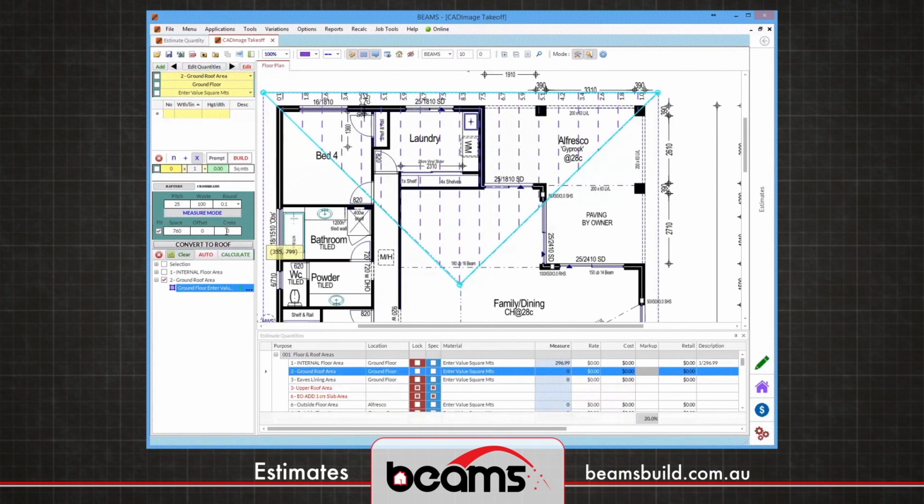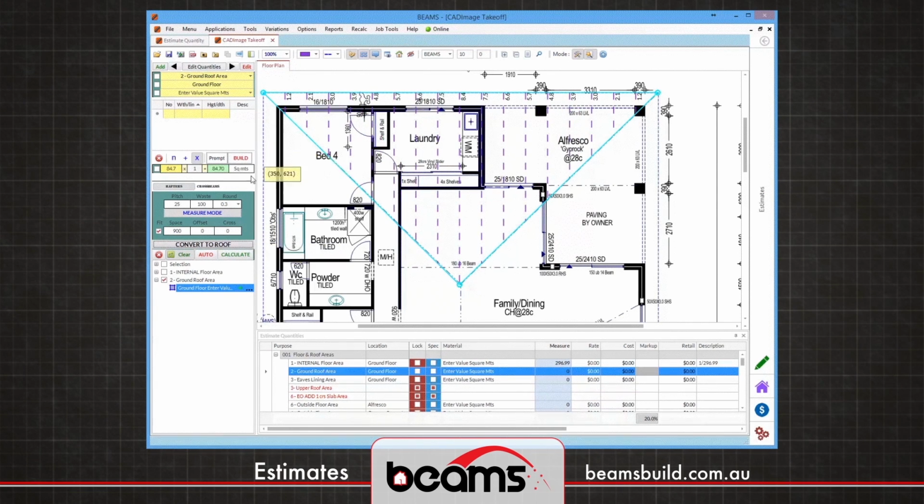convert to roof. It has now designed all the roof sheets required for that job, which I could simply go and order as required. Equally, if I want to change that, rounding to 300 increments, and let's change our spacing to 900 centres, we now have all the sticks required to do the roof timber for that particular roof panel.